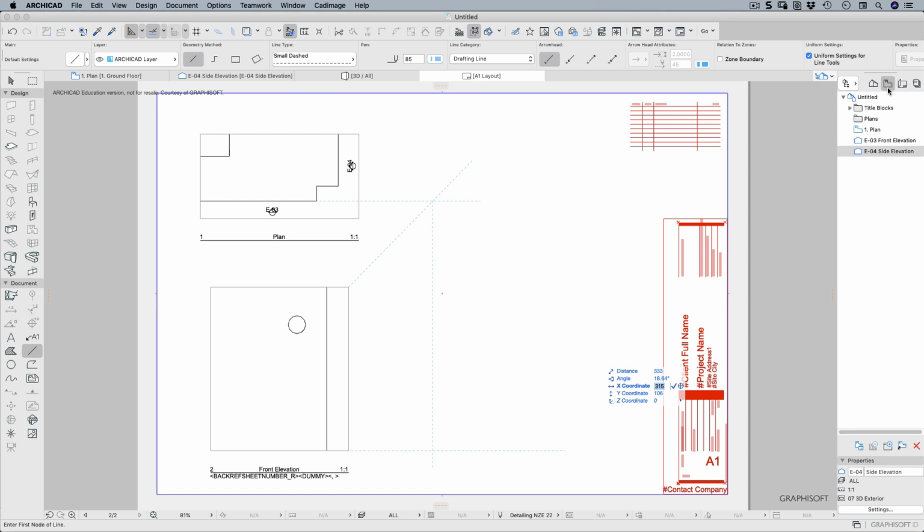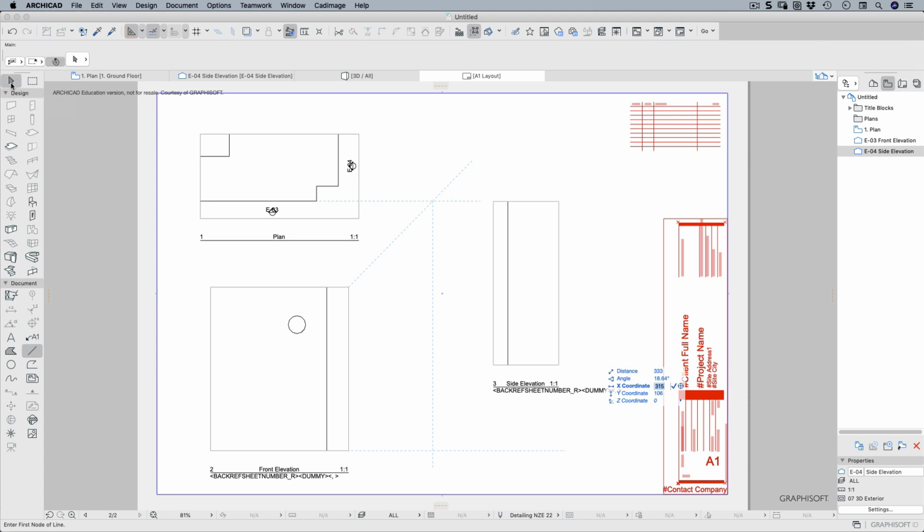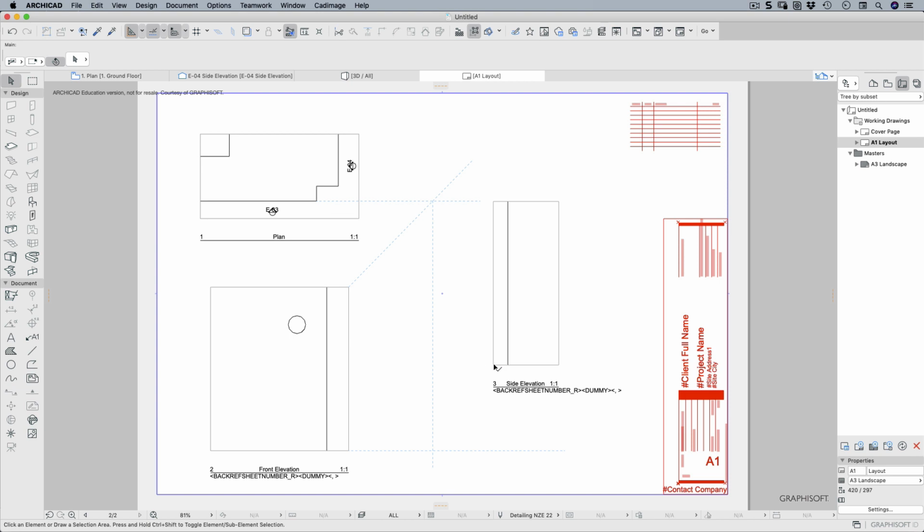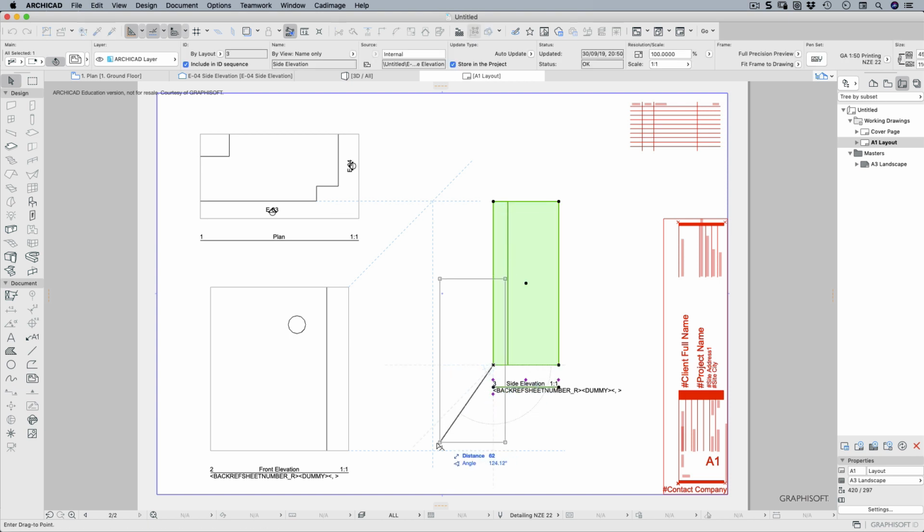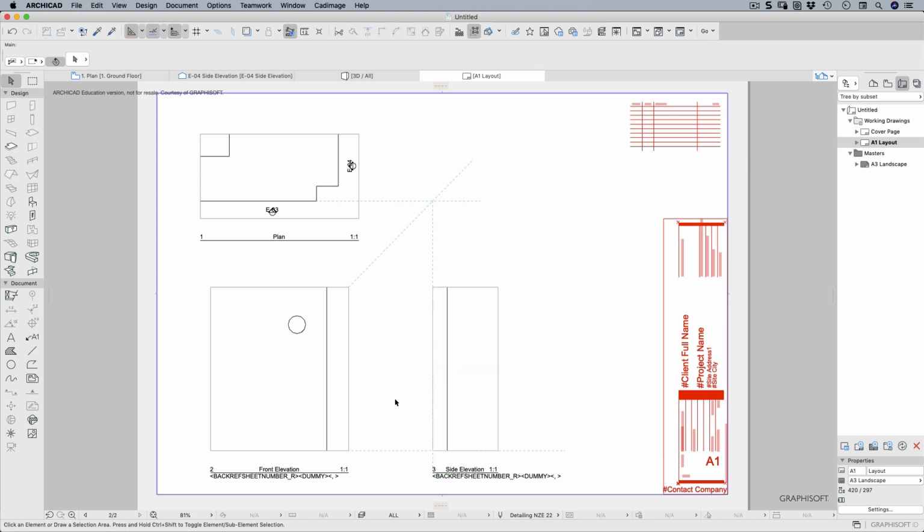Back to our view map, side elevation, let's drag that in first. There it is there. I'm going to use my arrow tool, and I'm going to get my arrow tool at this corner here, drag it, stick it in that corner there, and click. And so there it is, my elevations all line up. So that's just a very quick introduction to creating your elevations, my front, side.